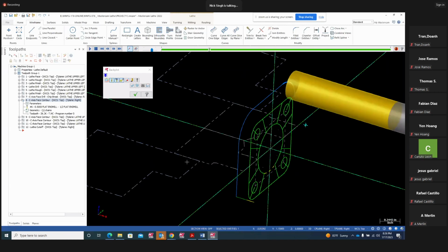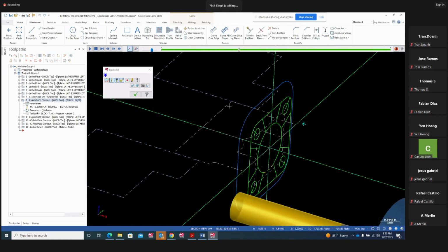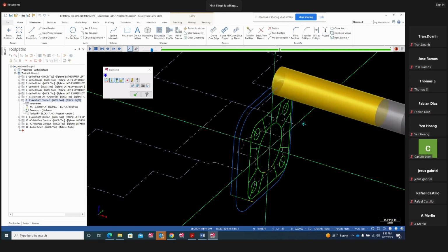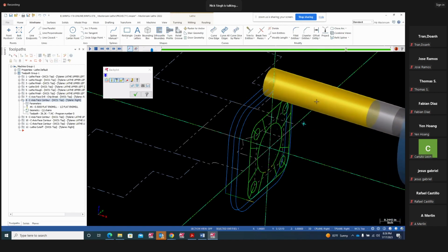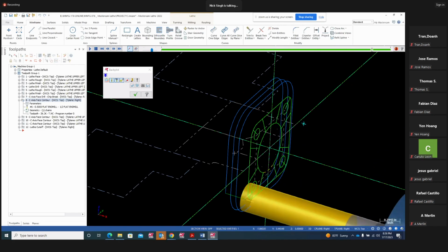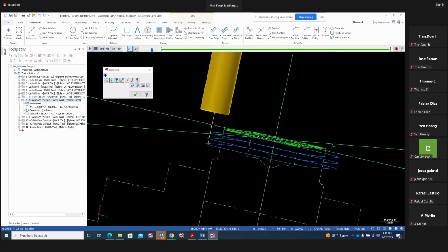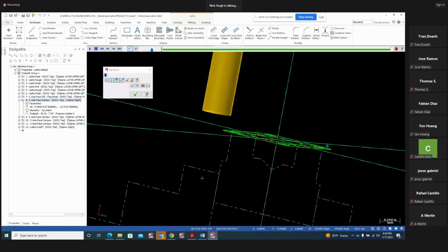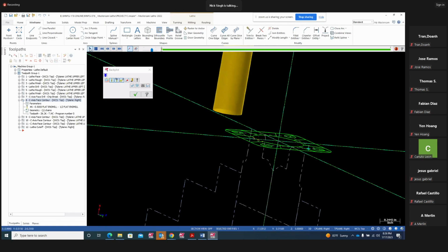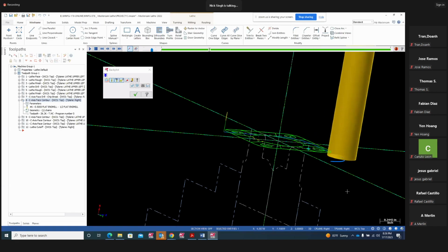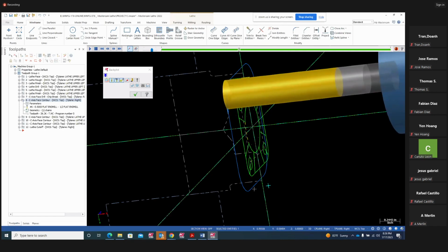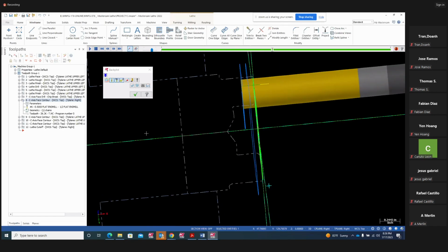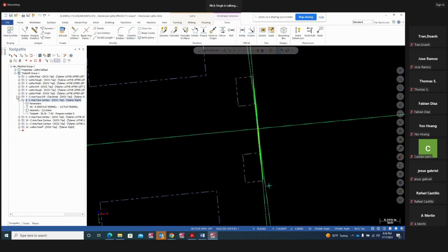So now your spindle is going to sync with your X and C axis. Your tool now, this guy right here, the yellow tool, is turning at 2000 RPM. It's working just like a mill. If you look under mill, it works like this, same thing. Looking from like that, it works like the mill, but it's cutting on the lathe on your right hand plane, just like this. That makes sense? I'm going to go ahead and draw this so you guys can see it.